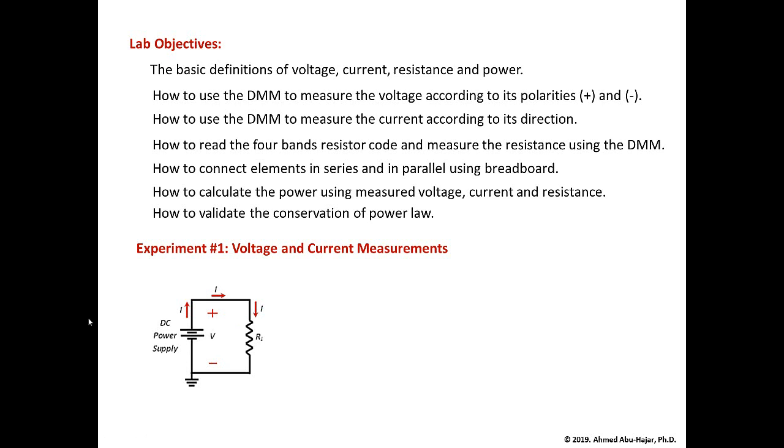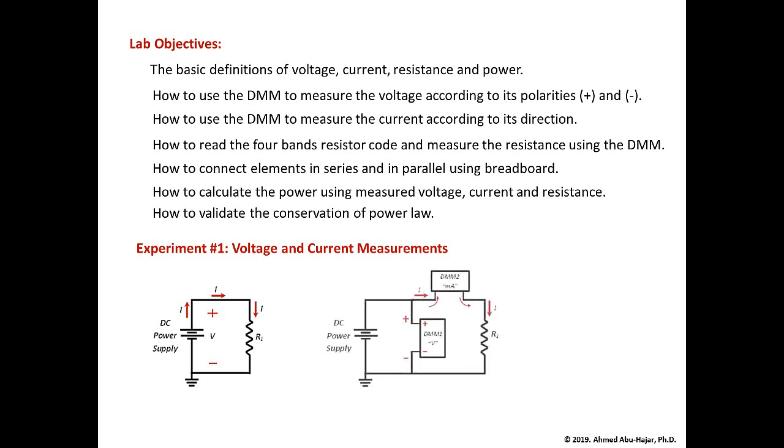In any case, you need to build the circuit using the breadboard, and then you need to learn how to measure the voltage and the current using the DMM. To measure the voltage, this DMM1 will be used across the power supply. The way you want to do it is configure the DMM to measure voltage, and you measure the voltage across the element.